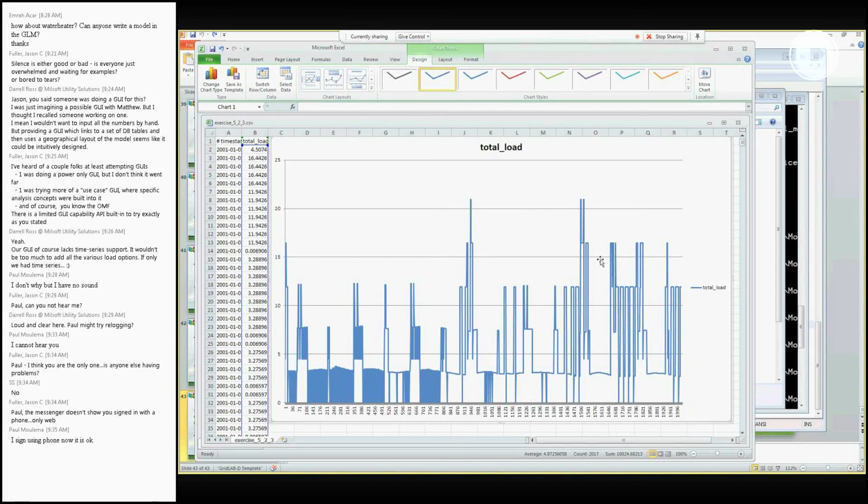So you can see here, because I believe this is mostly driven by the air temperature on the HVAC system, we have a pulse train that's very close together. So we're consuming a lot of energy because it's hot outside, versus over here where we're seeing it's not very hot outside and the pulse train is elongated. So it's these kinds of effects that we're really trying to capture by modeling these in this way.